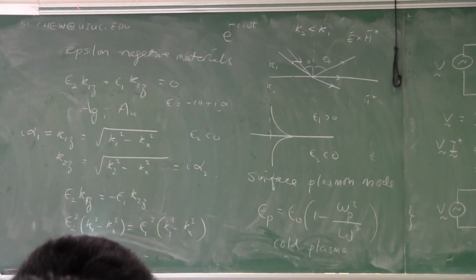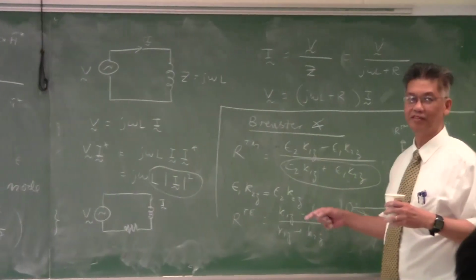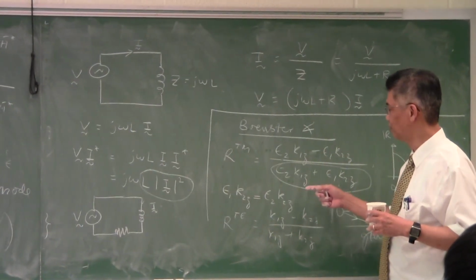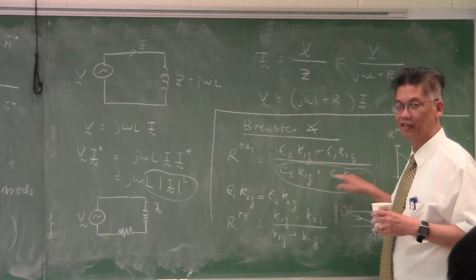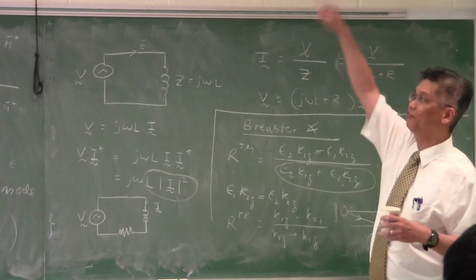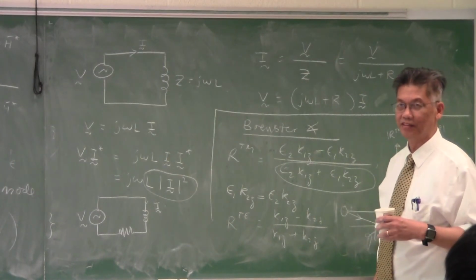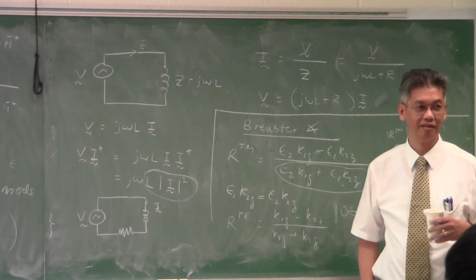This actually makes things happier, because if this thing does go to 0, it means that the reflection coefficient is infinite. That's not physical. So the reflection coefficient will only show a peak when you hit the situation where these two cancel each other. You see a reflection peak, but not an infinite peak, which is not physical. It will have a finite peak due to losses in the system.